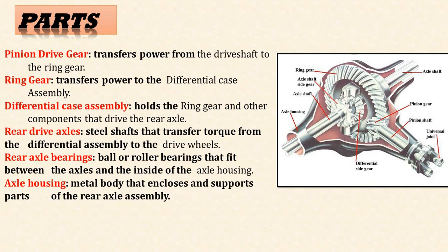It consists of two planet pinions, two sun pinions, cage, crown wheel and bevel pinion. The crown wheel of final drive is bolted to the cage. The sun pinions mesh with the planet pinions and are attached to the axle shafts carrying the wheels. The cage is provided with a cross pin or spider depending upon whether there are 2 or 4 planet pinions.